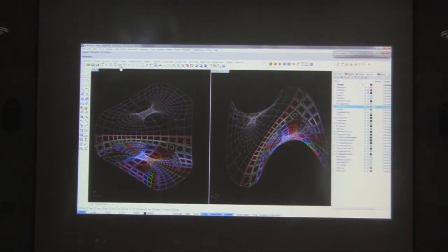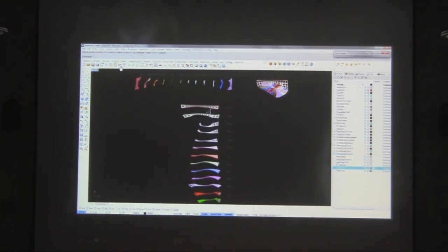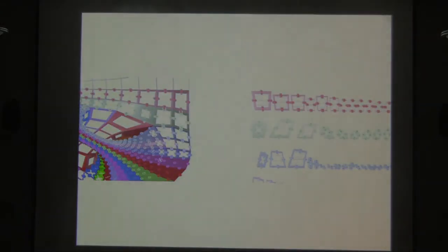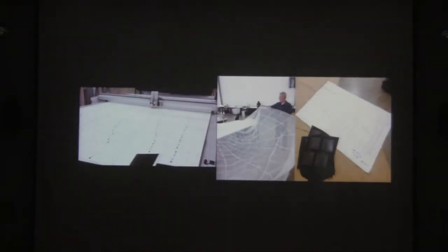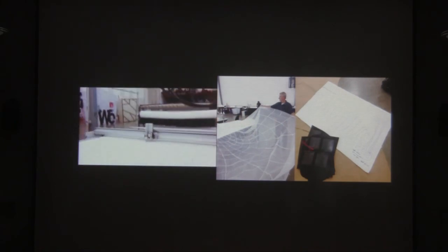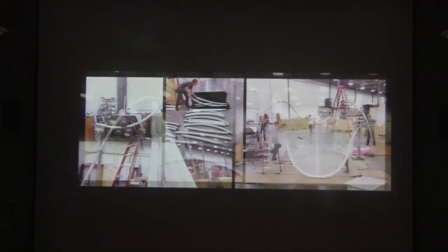Those cells get mapped, then put out into 2D space, unrolled, and from there we go to fabrication from those strips. Those strips, as I said, get unrolled and arrayed into strips, again CNC milled on a cutter here. Then the photovoltaics get applied to it. The perimeter frame is CNC bent. Everything slip fits, like just a series of tubes.